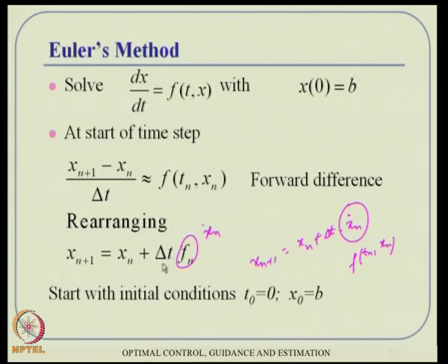For example, delta t is 10 to the power minus 6, that is 1 microsecond, and within that 1 microsecond the control update time is extremely small. In my knowledge I have never seen a control update frequency that small. Delta t being 1 microsecond, I have never seen. It's all millisecond level that I have seen. So you cannot do that, even if the problem demands it.